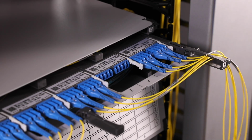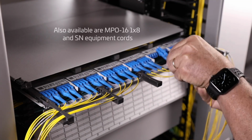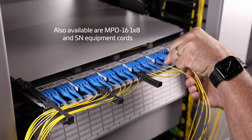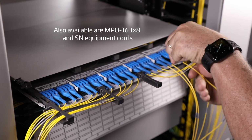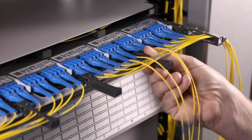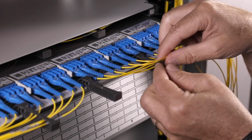Now you're ready to install the equipment cord. Here we have an MPO 8 to LC duplex cord. Install the equipment cord in the MPO module. After inserting LC connectors, reinstall patch cord clip and route the fiber.